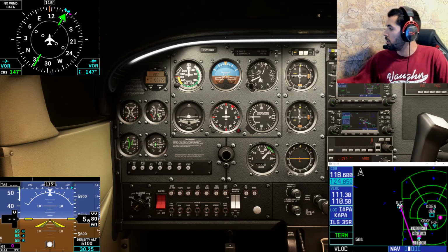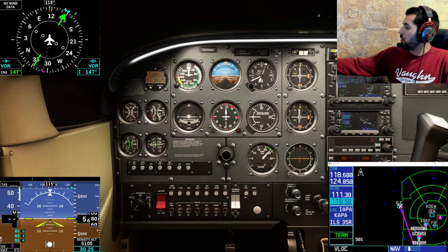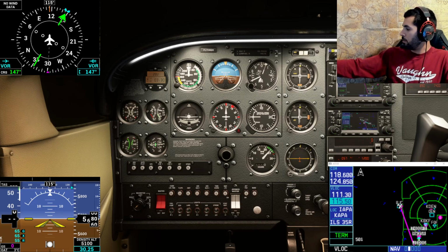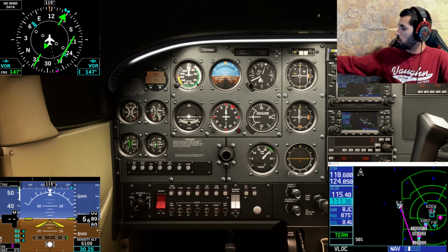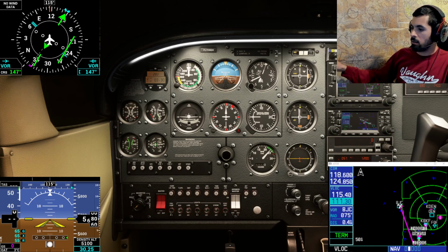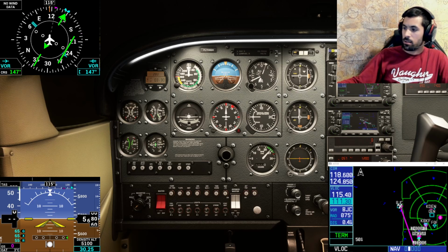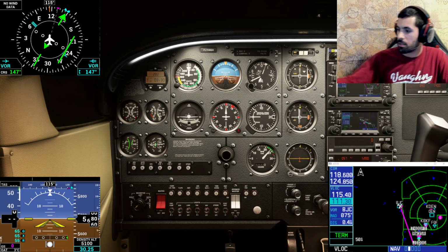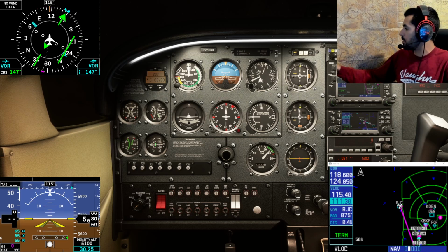I'm going to connect to Jeffco VOR. That's 15.4. So in the bottom right hand corner of my GPS, I'm just switching the frequency, and that'll allow me to kind of tune into it. So on my HSI, there's a green line that now pops up, and I'm just going to follow that.